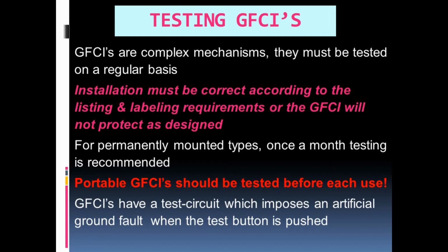For permanently mounted types, once a month testing is recommended. Portable GFCIs should be tested before each use. GFCIs have a test circuit which imposes an artificial ground fault when the test button is pushed.